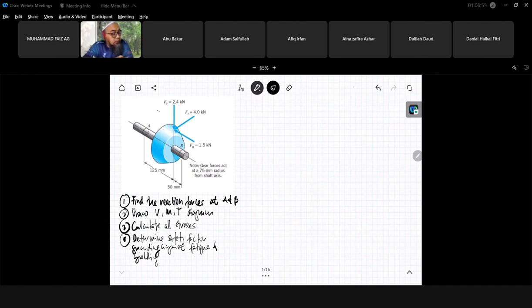So it has a shaft, and the shaft is supported with bearings A and B, and one end is free and one is coupled with an electric motor. And the load component is applied by the mating bevel gears as shown. So the loads are actually the radial, tangential, and axial forces.